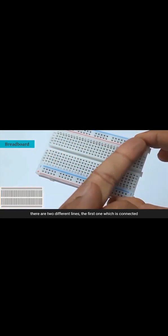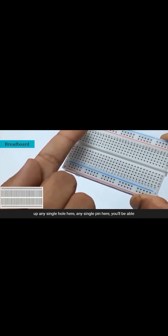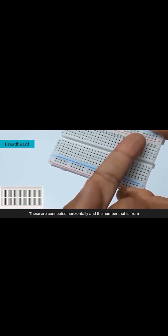If you look closely at this breadboard, you'll be able to see there are two different lines. The first one is connected horizontally and the second one is connected vertically. In a horizontal connection, if you power up one pin here, the connections throughout the horizontal pins will get the same voltage or potential. Similarly, as these are connected vertically, if you power up any single hole here, you'll get the same potential or signal throughout the pins. The topmost ones, the blue color and the red color, are connected horizontally, and the numbers from 1 to 30 are connected vertically.